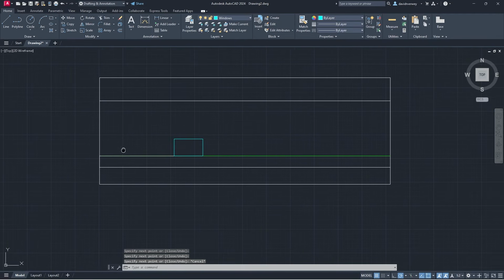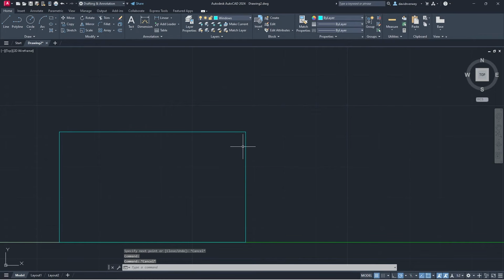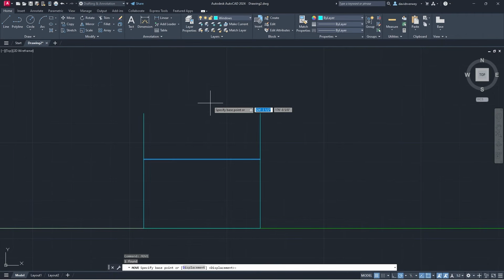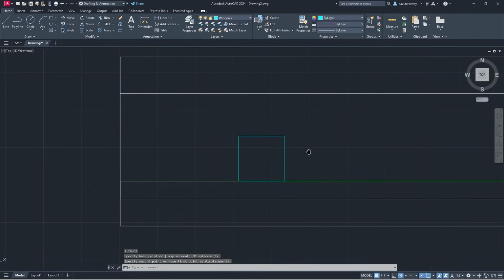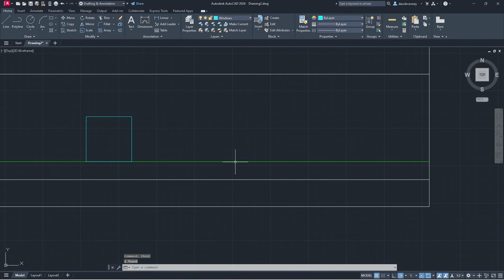And there's a window. That is a very small window, but it's what we have. Actually, you know what? I'm going to increase the size. Make it 2 feet higher. Grab this, move this up, put it there, erase our guideline, and there's our first window.